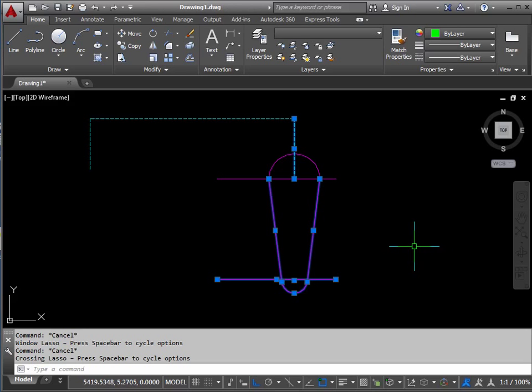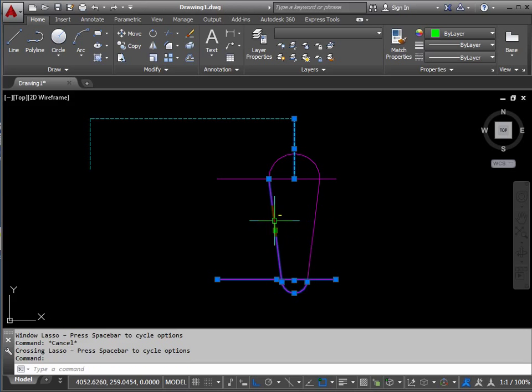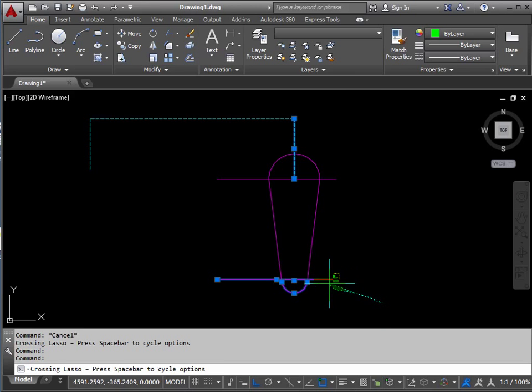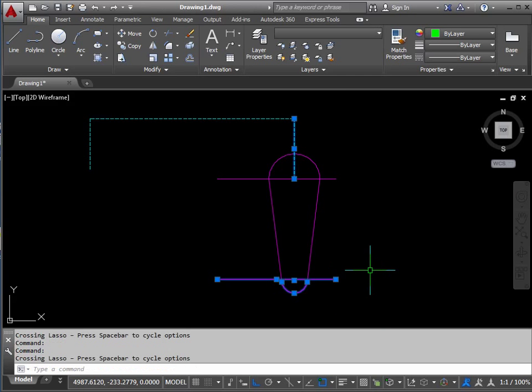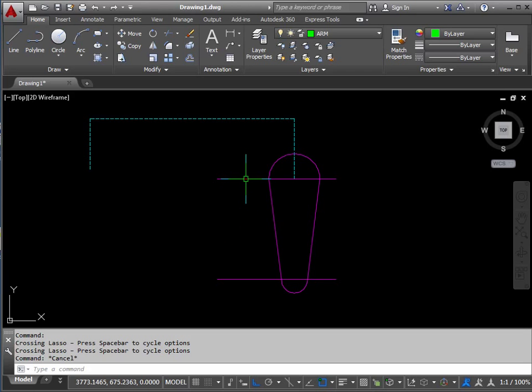If you want to drop anything out of a selection, you hold the shift key and either do single clicks or do these shapes for selection again. You have to hold the shift key when you're doing the drag one, I just found out. So selecting is quite easy. You can drop things out and re-add, and drop things out and re-add as many times as you need. But we're only changing 2 objects, so 2 single clicks is enough.